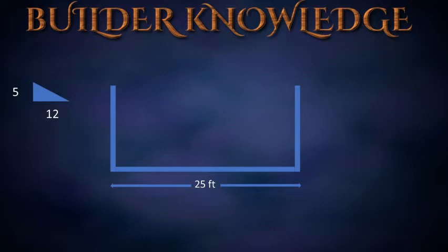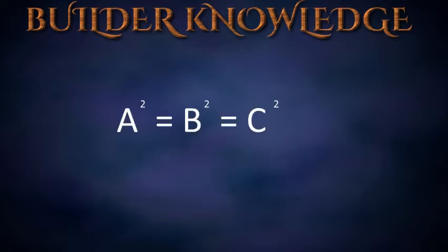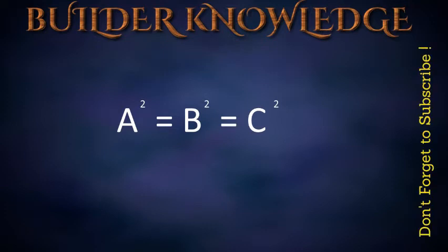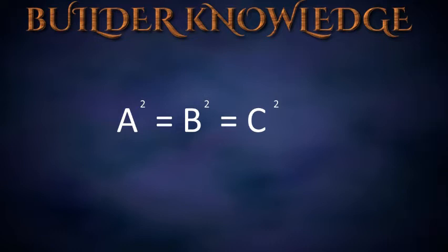13-inch projection. The Pythagorean theorem states, a squared plus b squared equals c squared. C squared equals 12 squared plus 5 squared. You may be a bit confused, so let's break it down. We have a 5-inch unit of rise for every foot or 12 inches. We want to find out the bridge measurement, which is also the hypotenuse of the triangle.